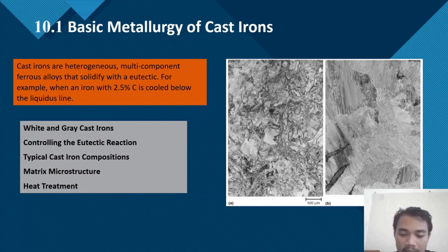Heat treating is used to relieve internal stress, improve machinability, increase toughness and ductility, increase strength and wear resistance, or reach a necessary step in the production process, that is, austempering gray or ductile irons, producing malleable iron castings, or annealing iron cast in permanent molds.